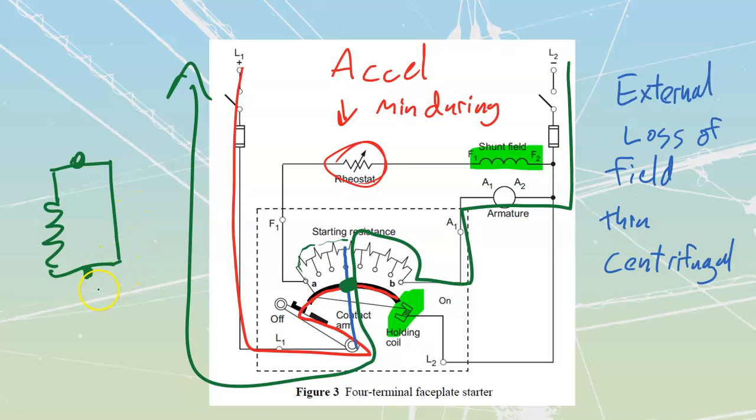We know that when we've got two resistances in parallel, the overall resistance is always going to be lower than the lowest one. So it's not going to give us more resistance in there, but there will be a tiny, tiny amount of current that will travel through it compared to a much, much larger amount of current that's going to be going through the actual contactor. So let's not worry about that little constant path that we have inside of there.